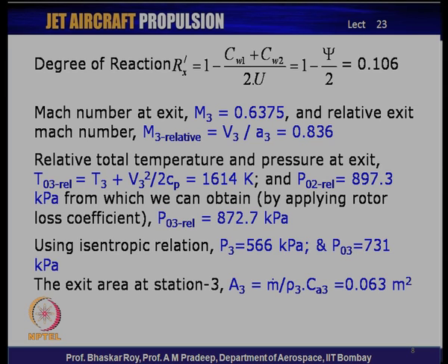Using the isentropic relation, we can now find the stator static values, that is P3 as 566 kilopascals and the total pressure is 731 kilopascals.